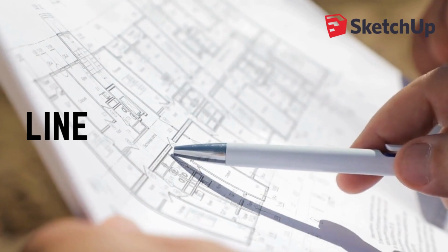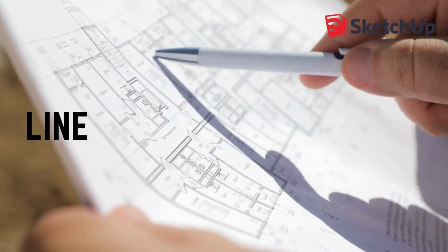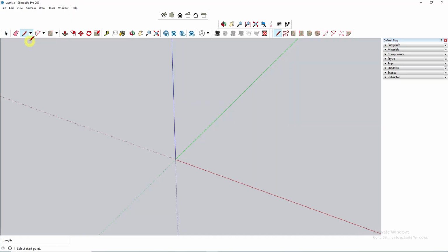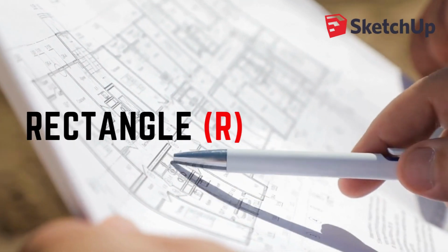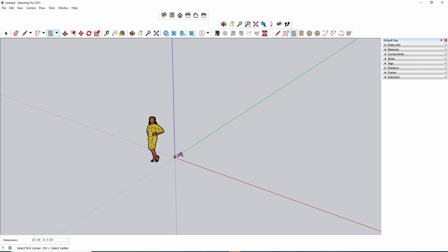Line. This tool draws lines, also known in SketchUp as edges. If you're finished making lines but the tool has started a new line, press the Escape key. Rectangle. To draw a rectangle, click one corner and then click the opposite corner. If you want to draw a square, wait to see the square pop up before clicking the second corner point.